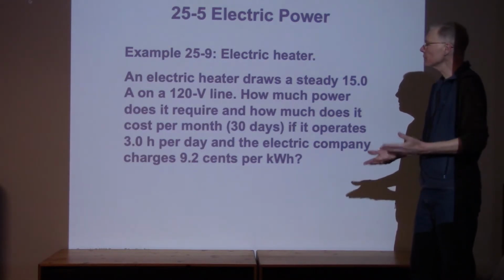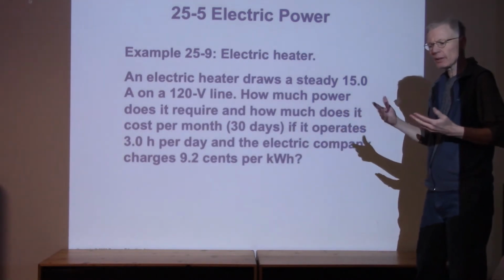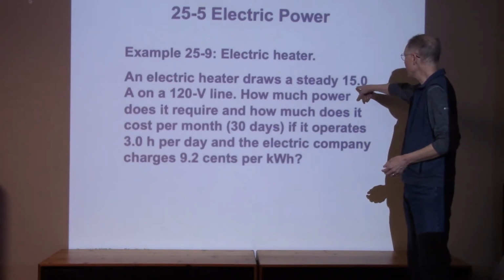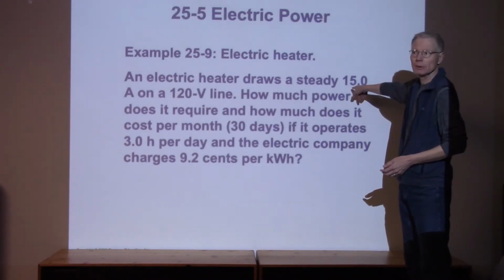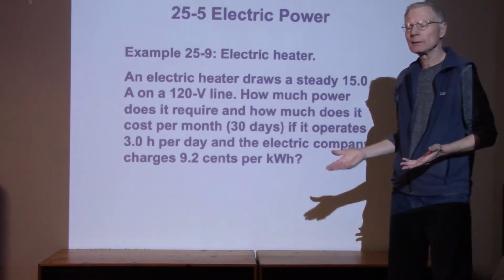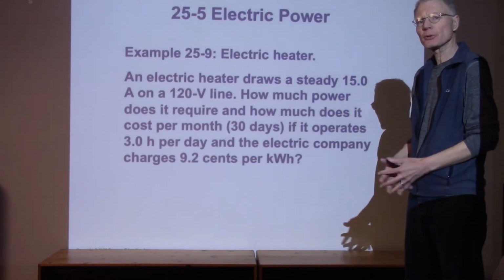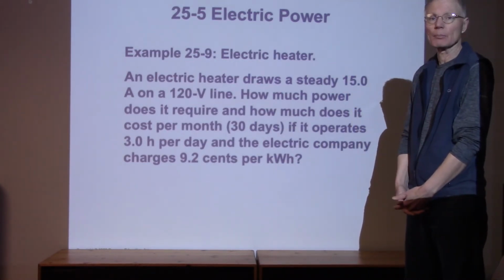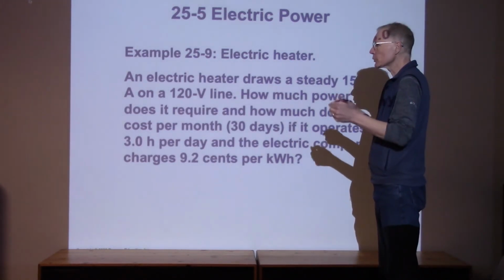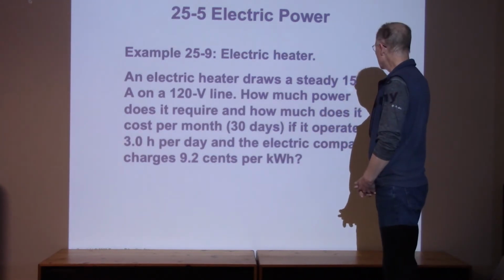If you're familiar with amounts of current in household wiring, that's a lot. You could have a fuse or a circuit breaker that actually maxes out at 15 or 20 amps. In my house, I've got a pretty modest electrical panel. There are 5 lines, and each line has a circuit breaker set at 20 amps. At 20 amps, it's considered high enough that the wiring could start heating up and possibly cause a fire.